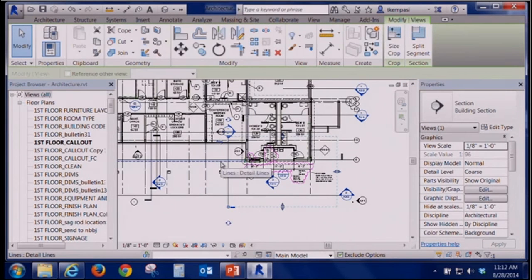So a few controls to the graphics on the section in plan. Again, there's a bunch of things that are blue here that we can pick on and control. For starters, at both ends we've got these little cycle arrows, and this will just cycle through what the head at both ends looks like. So if we want the callout at one end and just a tail at the other end, or if we just want a line, or whatever the case may be, however we want our graphics to look for the documents we're putting together.